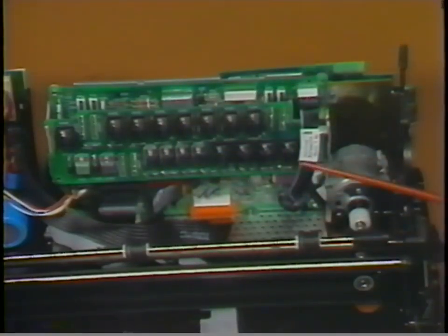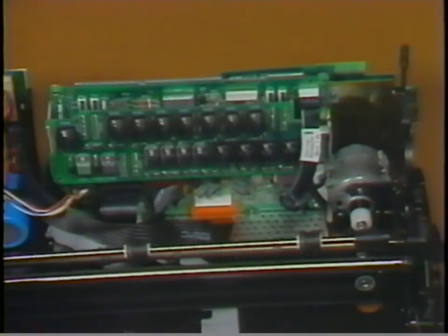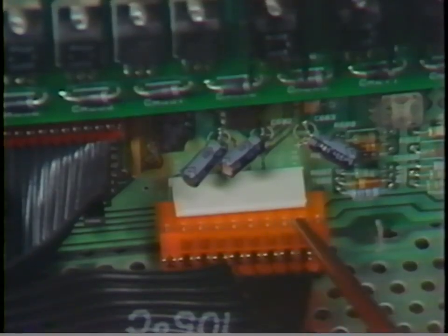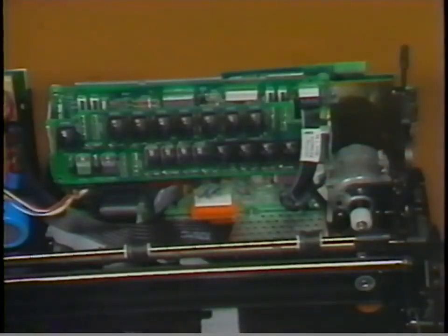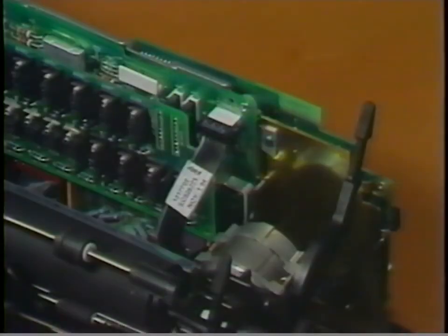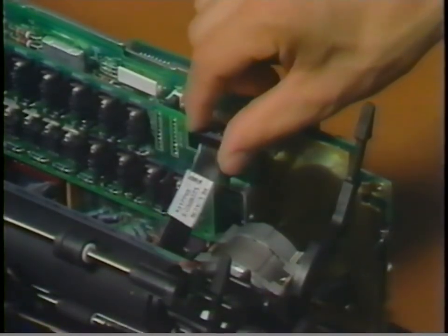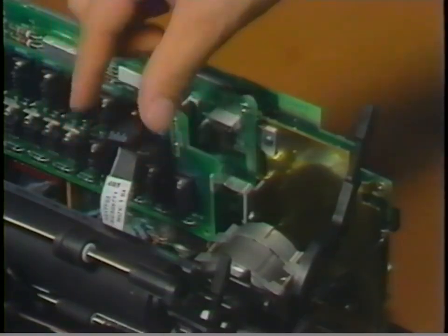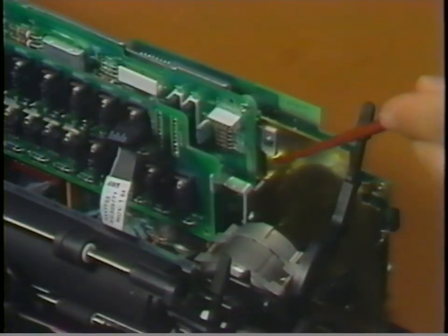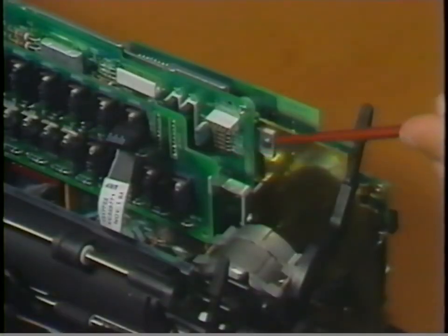This is the system cable connector J5P. The system cable connects the printer board to the function board. This is the power supply connector J6P. The power supply and system cable connectors have a blank pin on each side of the connector. Removal of the transport motor connector allows access to the sense pad. The sense pad is used to check for the correct operation of the homing sensor. Let's see how this is done.